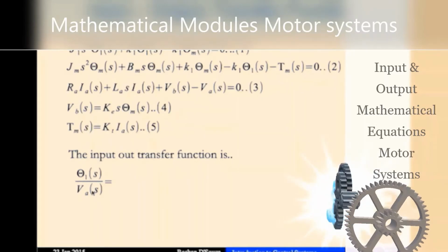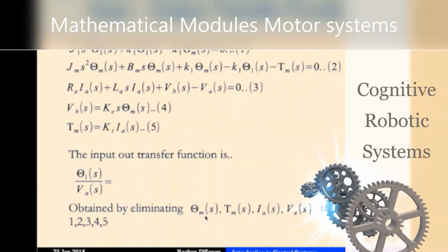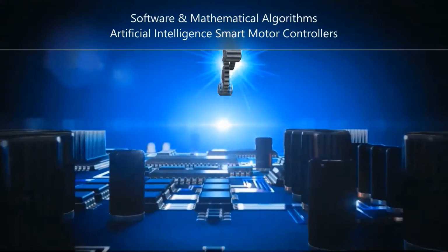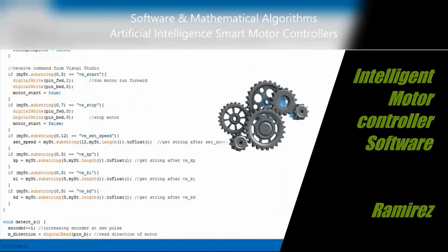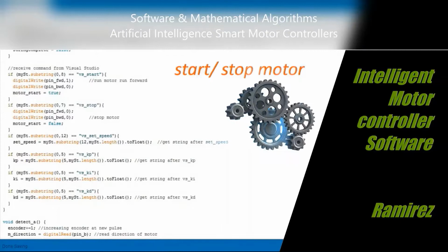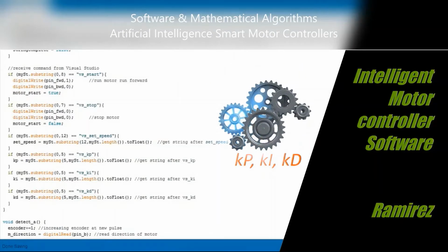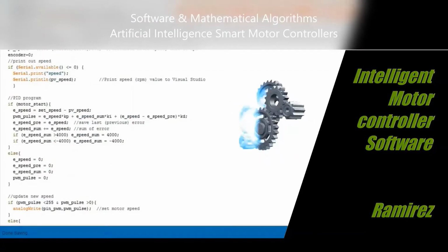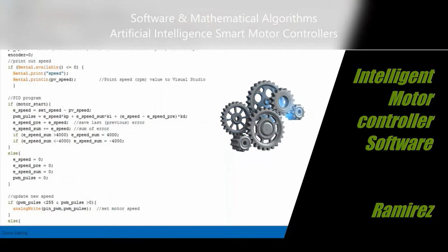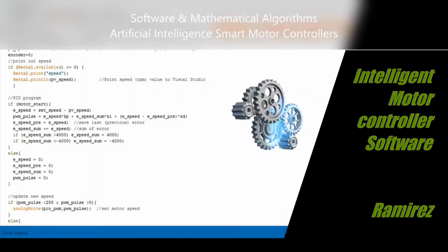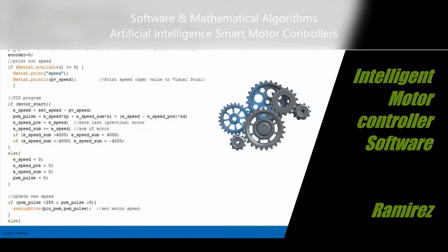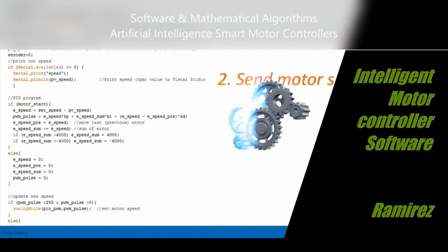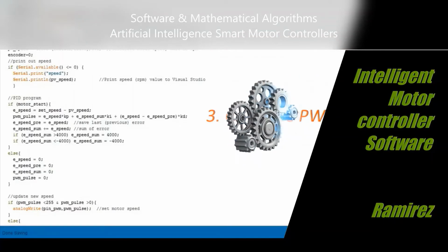A pulse width modulation (PWM) signal is a method for generating an analog signal using a digital source. A pulse width modulation signal consists of two main components. They define its behavior, which is a duty cycle, and frequency. The duty cycle describes the amount of time the signal is in a high on state as a percentage of the total time it takes to complete one cycle.